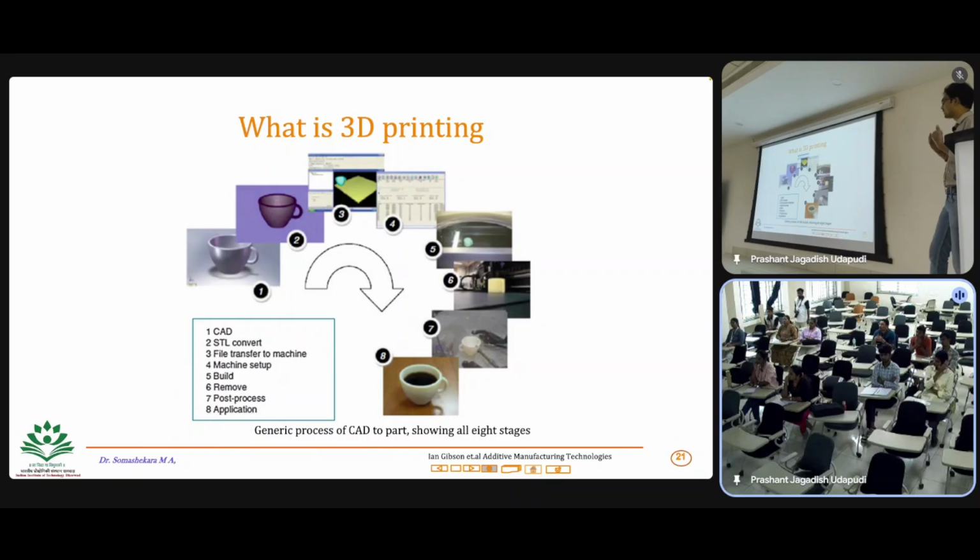And then, as you know, the machine only understands G code, which means you may have an STL file, but that doesn't mean you can straight away print a component. You need the sliced version of it, where you slice the model and combine the corners, and then you stitch the corners to form one layer. To transfer it, the machine only understands the G code language, so we need a format that the machine can understand. That is one part of the software, where you process the file.